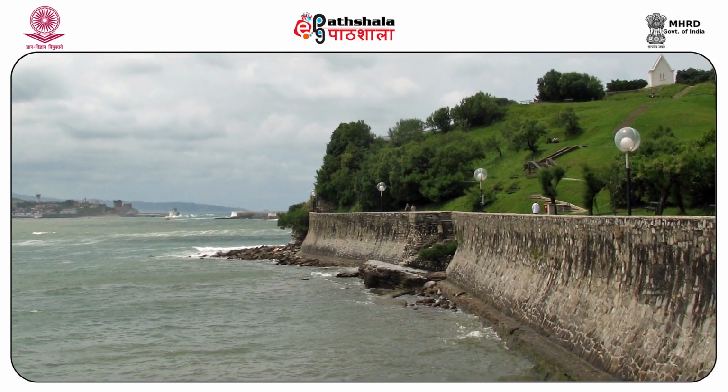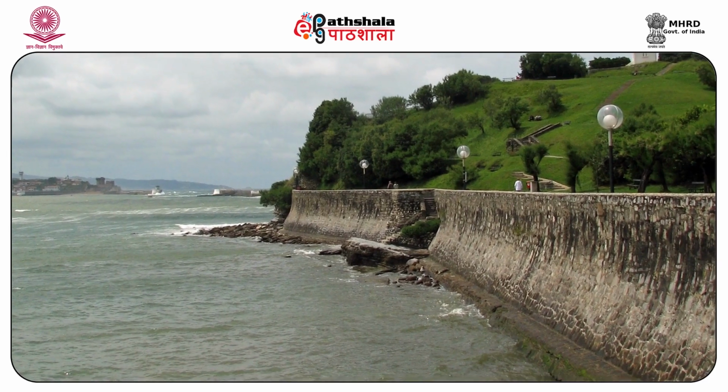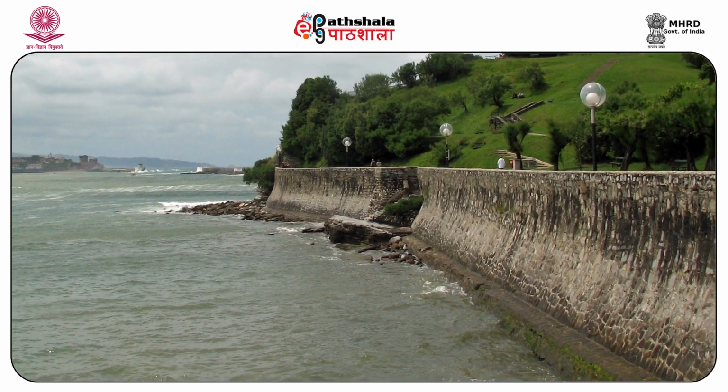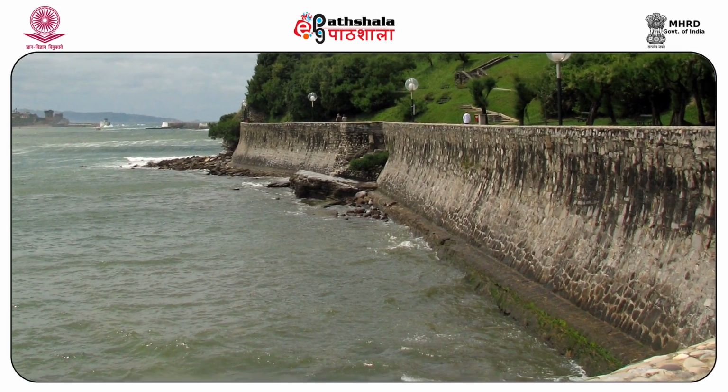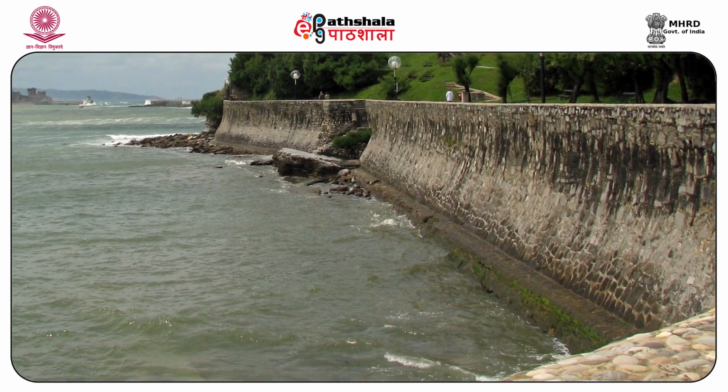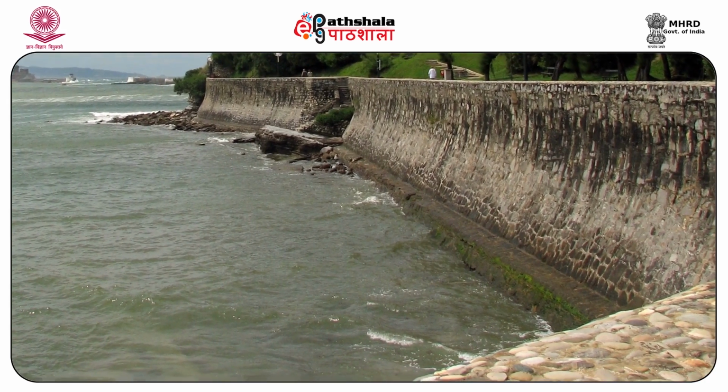Apart from this, sea walls can also be made, but they have not been found very successful, because if the water level goes above the height of the seawall, then there is permanent flooding on the back side of the wall. But there are places where sea walls have been made with a very strong foundation, which is called bulkheads, because to make that wall withstand the continuous action and impounding of waves, the lower part of those walls has to be very strong.